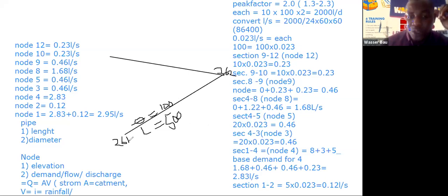If you put the elevation, some people also put MOSL, which is meters above sea level. Then that's not all though. Sometimes you can also write the invert level. You also put the slope. So this is how to detail a water reticulation drawing.